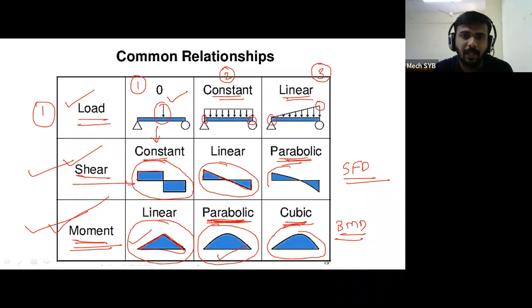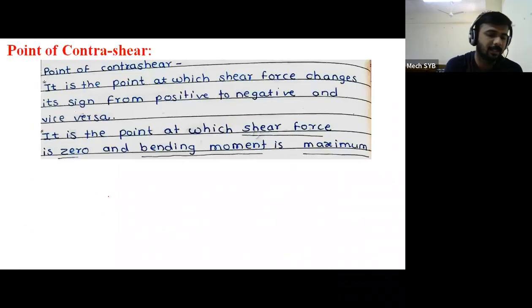Okay, so this is the relation between type of loads, shear force diagram, and bending moment diagram. Now the next points, these are the two important definitions I have given in some of the introduction part. The SF and BM calculation we are converting into a diagram. Those diagrams are called the SF and BM diagram. Through these diagrams we have to identify the critical points.